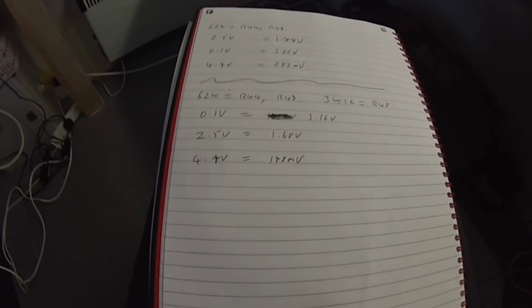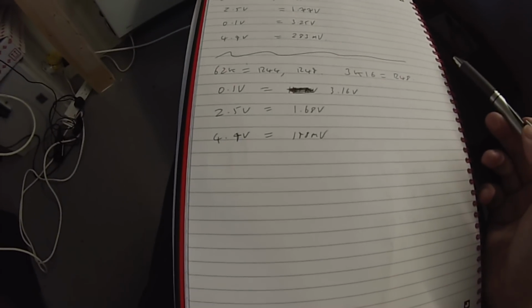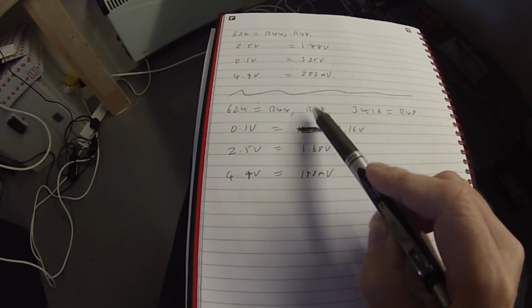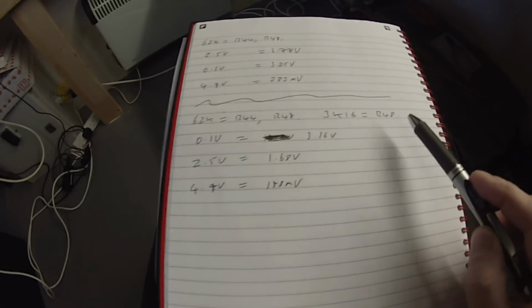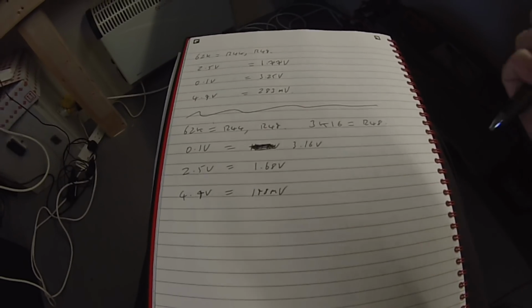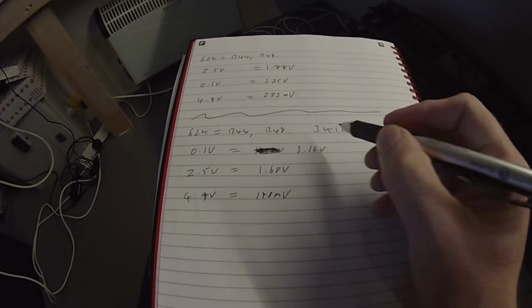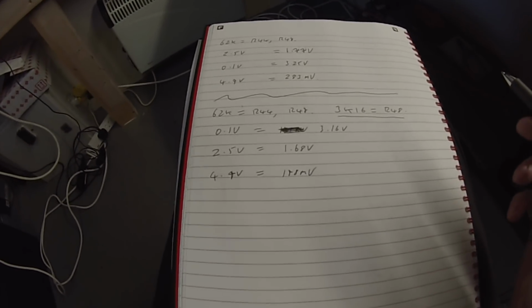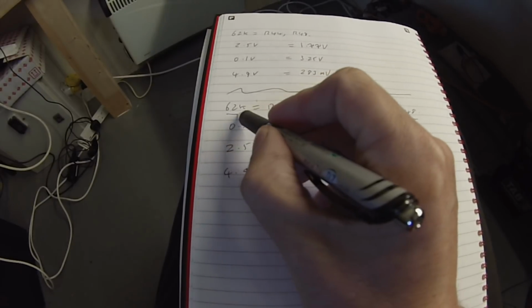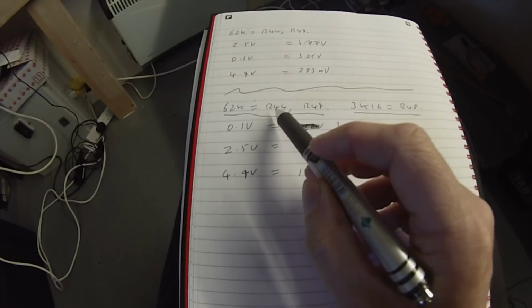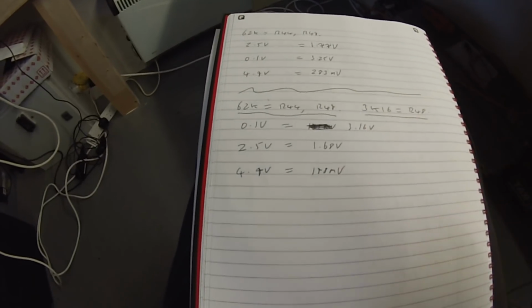What we also need to do is change some resistor values. R44 and R49 need to be 62K, and R48 needs to be 3.16K. Now, this was something that the Team A guys actually did highlight to me before they stopped talking to me, but unfortunately they didn't go far enough in their component value changes, because what we really need is the 62K in R44 and R49.